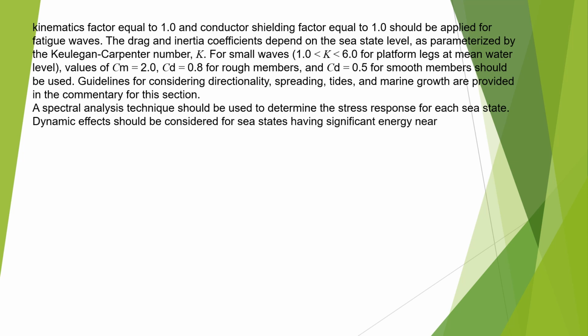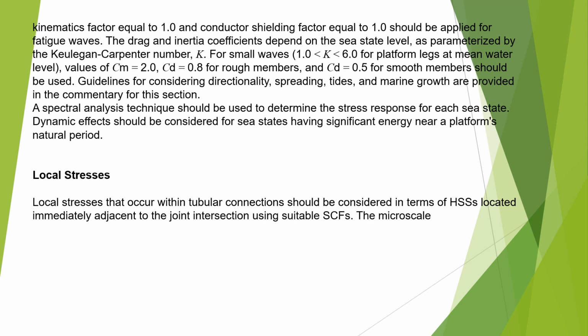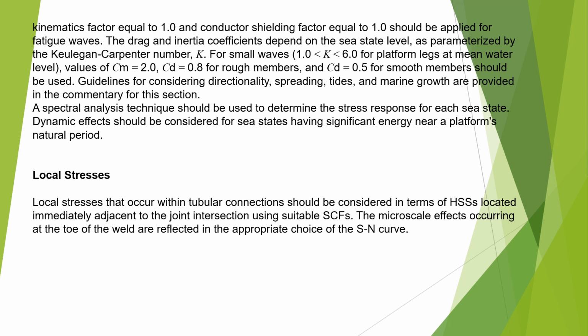So CD is 0.8, high, for rough members and low, 0.5, for smooth members. CM is the same only. Guidelines for considering directionality, spreading, tides and marine growth are provided in the commentary for this. Spectral fatigue analysis: spectral analysis techniques should be used to determine the stress response for each sea state. Dynamic effects should be considered for sea states having significant energy near the platform's natural period.